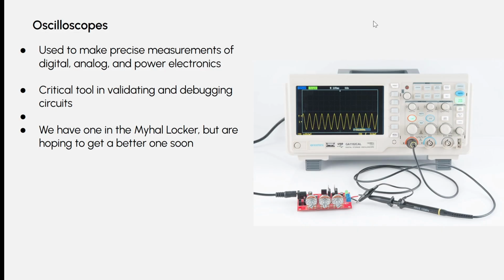Most oscilloscopes are not really good for RF. When you get into RF stuff, you have to use special tools, because the oscilloscopes that can measure RF frequencies are hundreds of thousands of dollars. So you end up having to use fun tricks to bring your frequency down to a readable range.